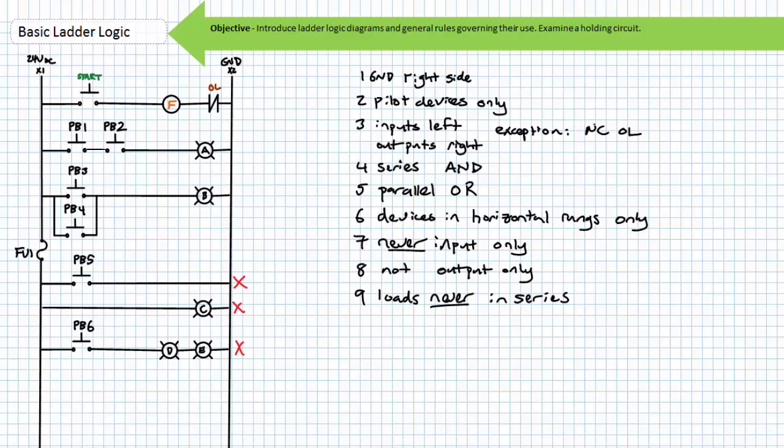This is wrong. Both lamps would be dim if they operate at all. This is to suggest the maxim one load per rung. Load devices must be placed in parallel with one another if they are to be simultaneously energized. The closure of push button 7 would energize both lamp F and lamp G with a full 24 volts DC they are intended to operate at.